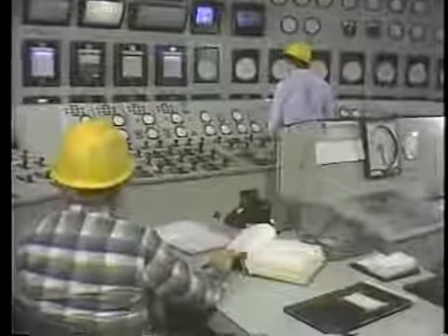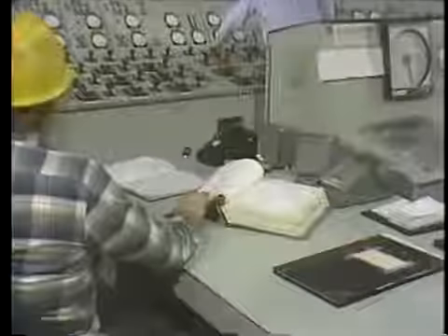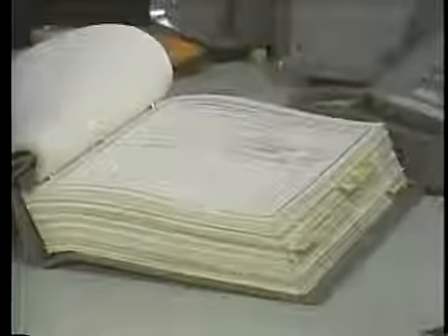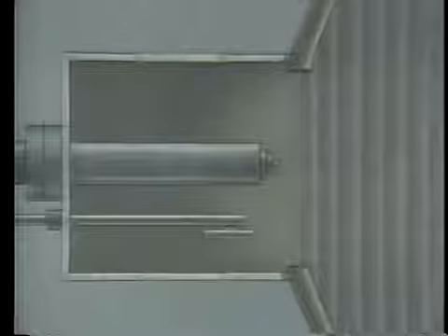The same thing can happen if a combustible mixture is present in the boiler prior to startup, and an operator sparks igniters without first purging the boiler. An operator can easily avoid these situations by carefully following plant procedures and purging the boiler before sparking igniters. Then, verifying that the igniters are operating properly before introducing air and fuel to the boiler.